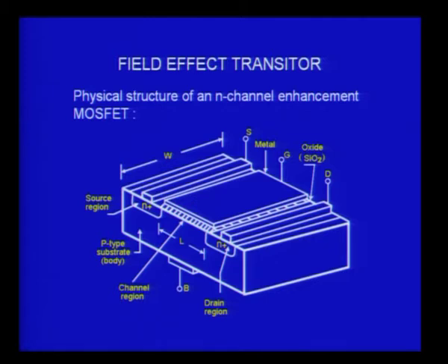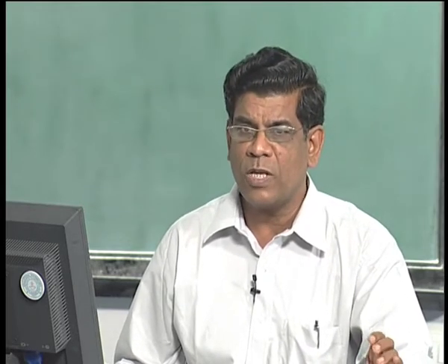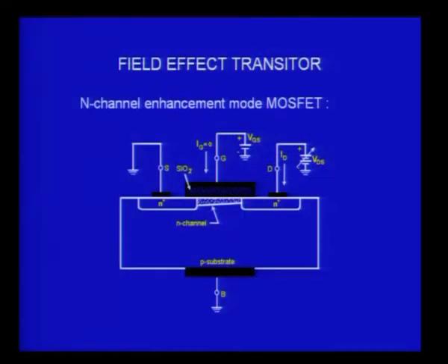This is a very important device. Again, almost all integrated circuits make use of this configuration, where the junction is formed in the normal junction field effect transistor, whereas here what we do, we actually use it like this. You have an N channel, you have a P substrate on which you make two regions of N with a gap in between.